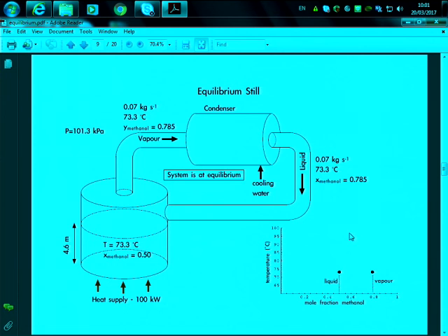Okay, so here, what we do in the lab is that we have the distillation column, well, a very small distillation thing, and then we have a heat plate, and then the students start running this type of system, and they record the temperatures. They record the temperatures here and the temperatures here, and the percentage of the mixture. Okay? For example, in the lab we have an ethanol water mixture, and then they record the percentage through a technique called refractometry, which tells us more or less the percentage of alcohol in the system. And through that, they are able to plot this type of chart.